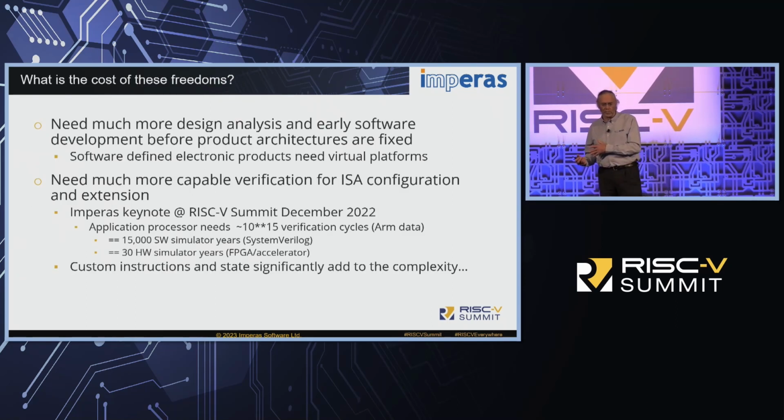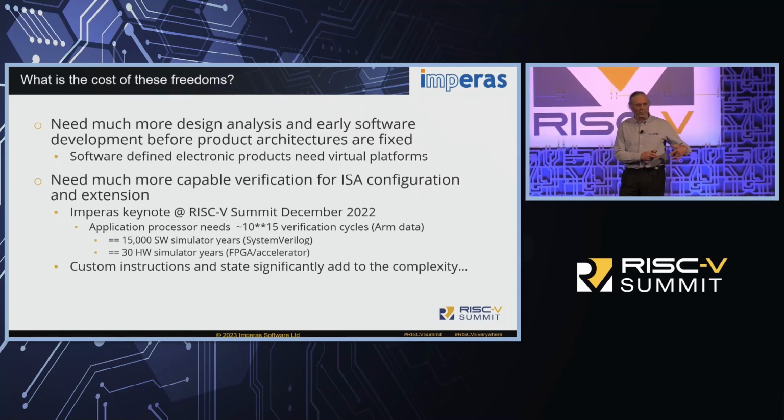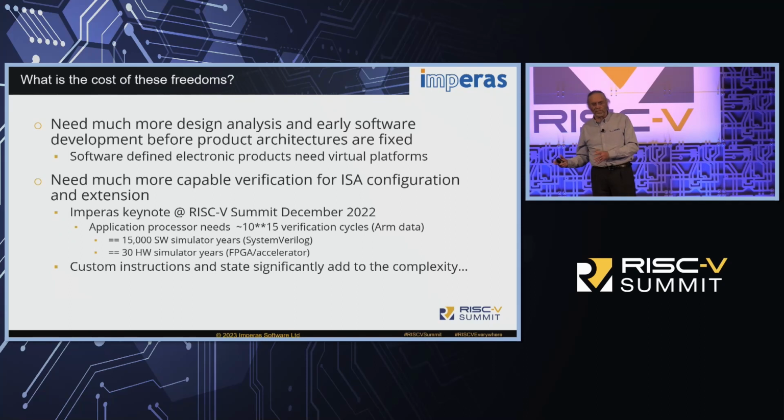It's the freedom, we think, that it enables. But there are always costs to these freedoms. If you're building your own technology, you've got to do much more analysis on it. You've got to get software running early to see whether the architecture you're building, this domain-specific processor, does what you need. Because with these software-defined electronic products, you have to verify that the software is going to run on it before you commit to the RTL and the costs of that. Simulation technology called virtual platforms is very much needed to get the software running. We've had people using virtual platforms a year before the RTL is even fixed, or before they've even chosen the IP related to it. So it's very important with software-defined products to do simulation early.